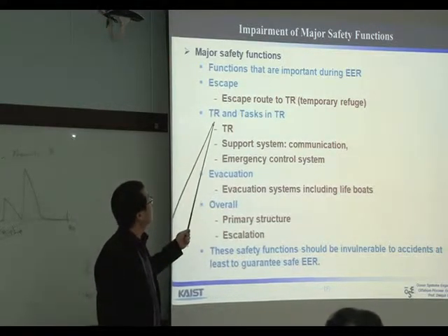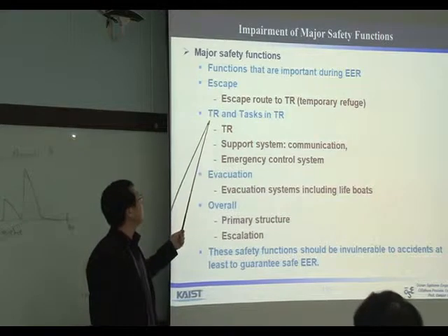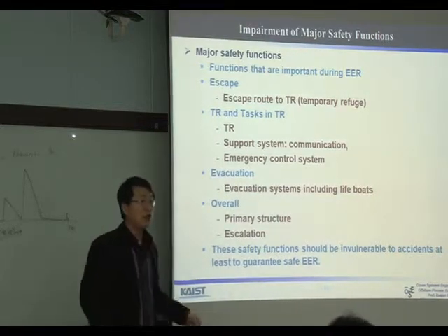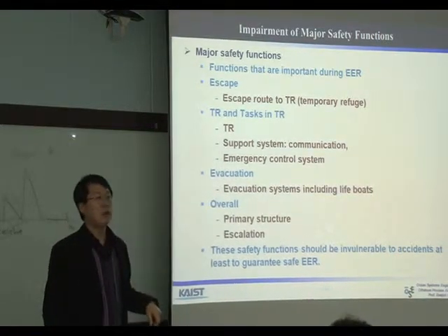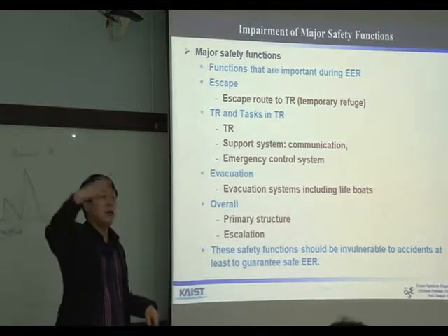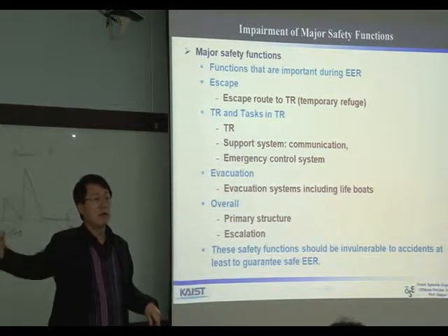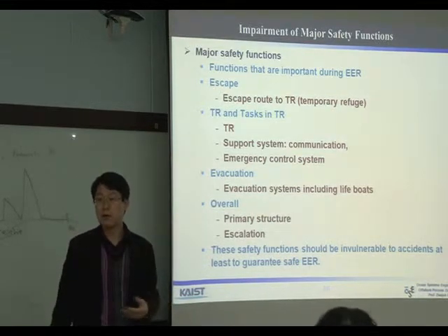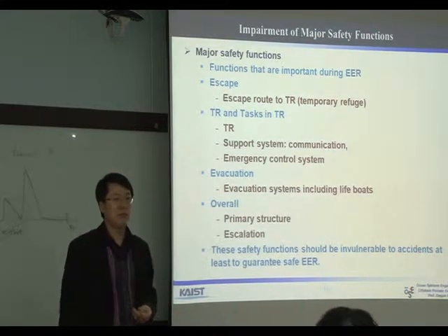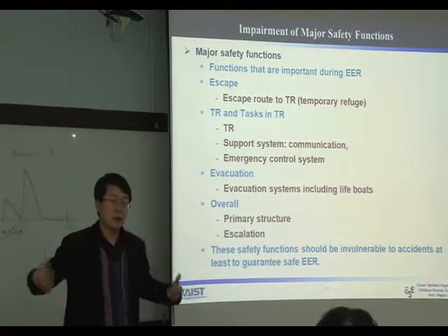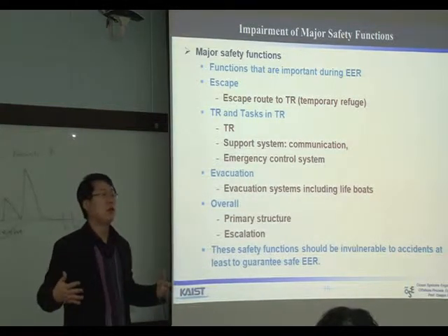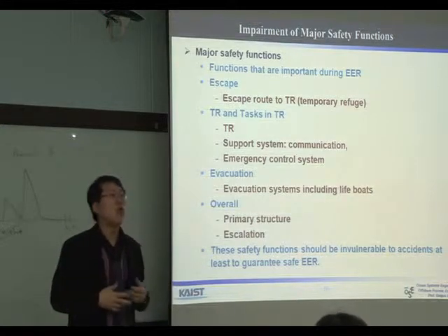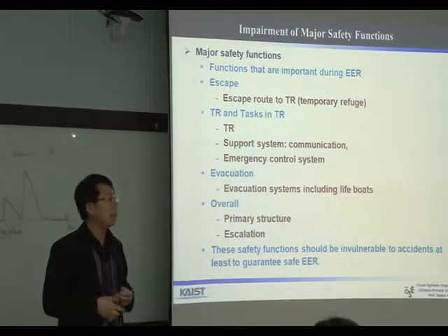TR, the temporary refuge, and the tasks in the TR, considering the tasks, the TR should be safe. There can be some fire outside the TR. If the TR is burnt by the fire, it makes no sense. So the TR should be strong enough against the fire and explosion.